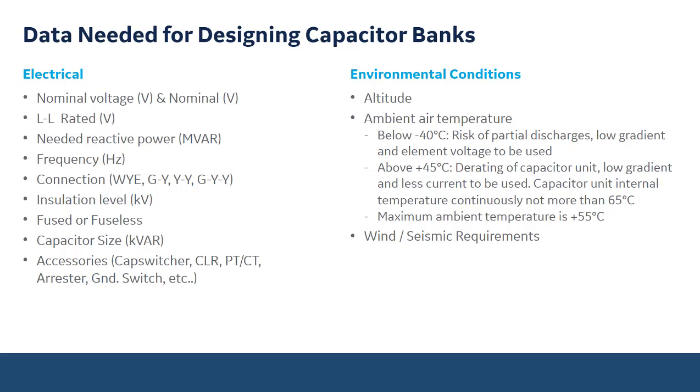And then for your protection, we're going to be using a potential transformer, or PT or VT. A CT would be a current transformer, and then some system protections such as arresters. Generally, we put an arrestor on each phase, and then a fourth on your neutral.